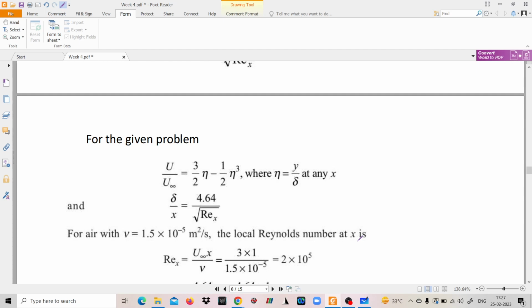For example, in this case it was a cubic profile, so you write the most general form of that cubic profile, and based on the number of unknowns you construct boundary conditions which are feasible for the flow characteristics inside the boundary layer. If you use any boundary condition, it will definitely give you some value for the coefficient. But finally the profile that you obtain will not be representative of the actual boundary layer flow case that you want to solve.